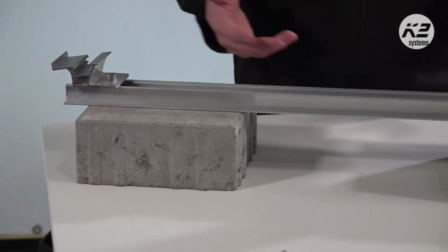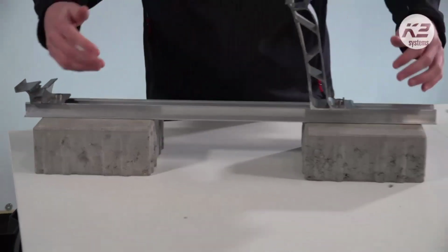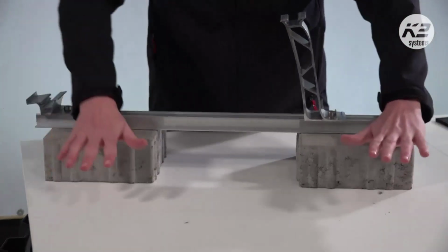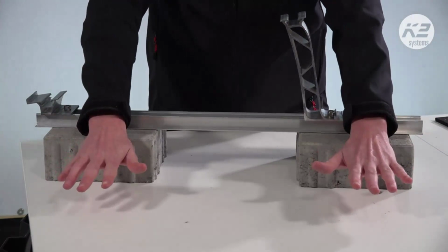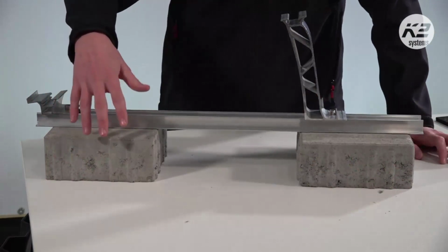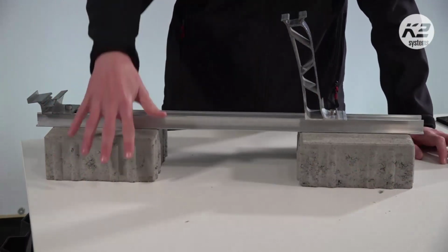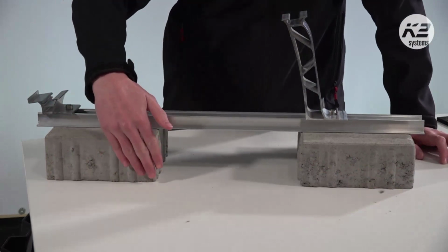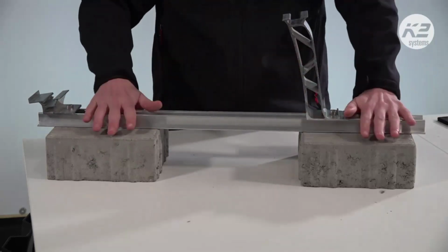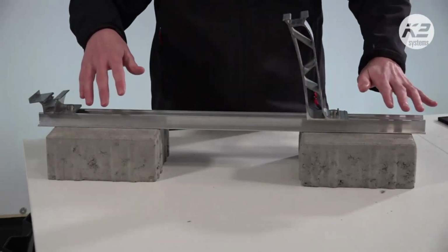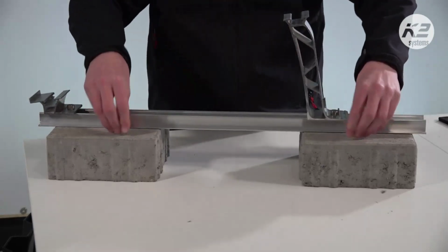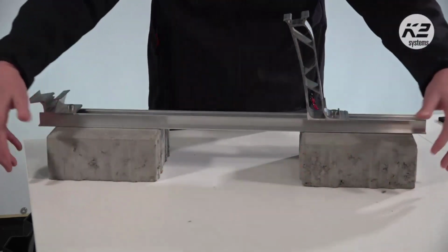But the idea is much the same with the PE plates. If you have gravel or the green roof, it's just going to sit at a rough height, whether it's 80 mil, 100 mil, 120 mil. And you can then either place these blocks just directly on top of this gravel, or you can dig into the gravel and place them down. If it's a new roof, you might just want to place the blocks down and place the gravel around it. And in this case, the gravel is not sitting on top as such, but it is going to nestle around it and hold it in place.